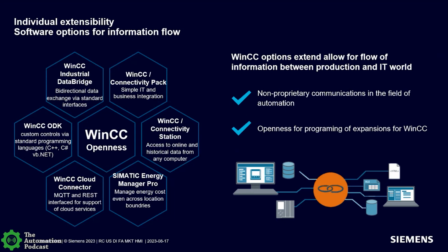But also, we've got a lot of WinCC cloud connector options out there. And you can get drivers such as the MQTT or the REST drivers, which will let you move WinCC data up into some of those cloud applications. So whether you want to use MQTT to push the information up into the cloud, or you want to use a REST interface to either pull information out of other IT systems or push information into IT systems, those are some of the newer drivers and features we've added to WinCC to work with the whole Internet of Things and the connected factories.